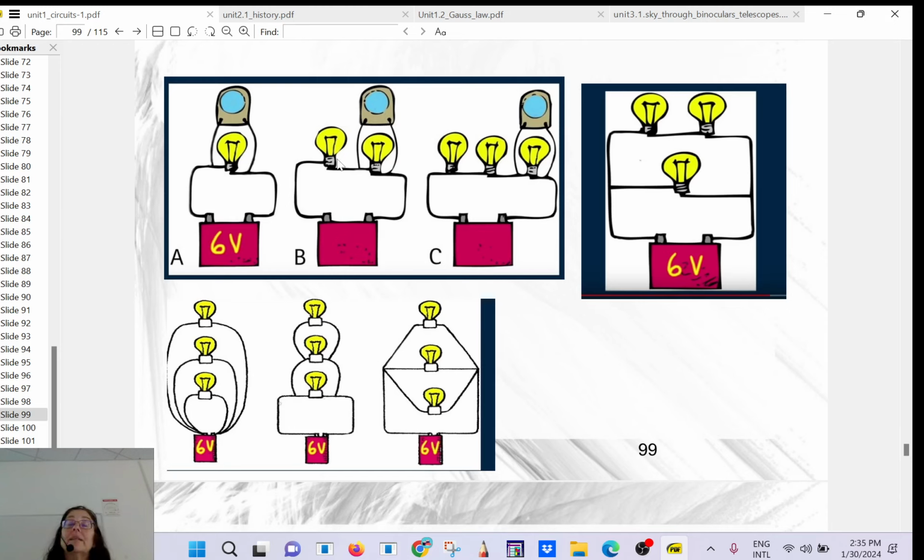So it's not happy. It's a circuit in series. So instead of getting the 6-volt drop, it's getting 3-volt drop. We suppose they are the same loads. In addition to that, the current will be divided by 2, because you multiply by 2 the resistance, and you divide by 2 the voltage for each one of them. So you divide by 4 the power. So not happy. What about the voltage drop here?